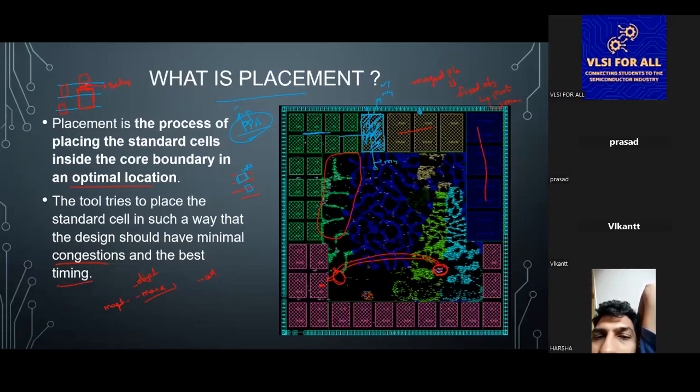Why this area will come, I'll tell. Inside that, they have used all this, so they want to preserve some space after the standard cell. So that's why they will add some extra margin. That is okay for us. Sometimes what we will do, we will fill this area with the keep out margin, to avoid some other legality violations, fake legality violations.